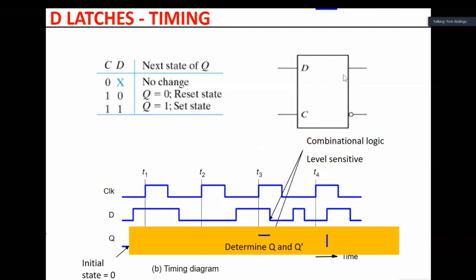In simple terms, when C is high, it is active high, the value of Q is the same as D. In another language, if C is low, it is in memory. Whatever was there in Q is kept. People were saying we should repeat, pay attention. You have to understand something before you apply it. So the first step is to understand this.